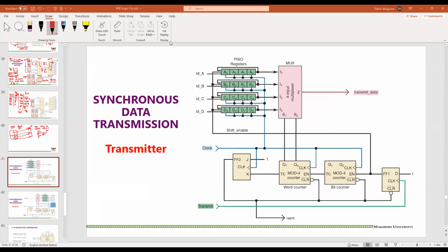So this is synchronous data transfer. It is synchronous, like serial. So you can transfer data synchronously. In this synchronous transfer, you transmit the data serially, but the synchronism is that you have the clocks, so you are shifting information. So let us see how this looks. This is a D flip-flop, which is at 1, meaning that this output flip-flop 1 will be 1 when we get the clock.